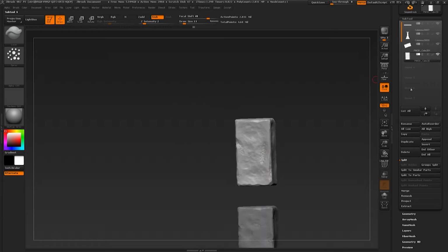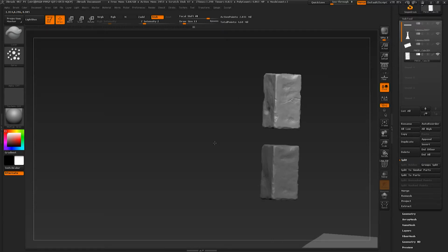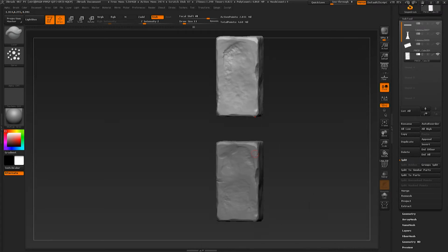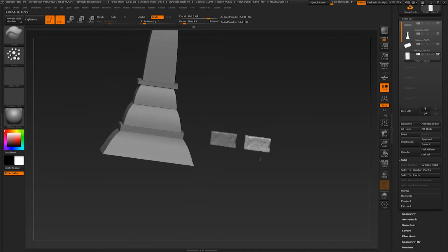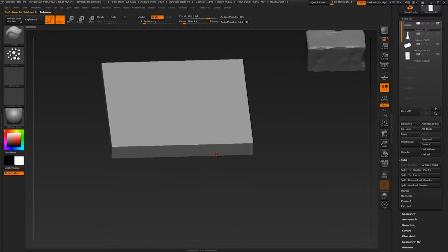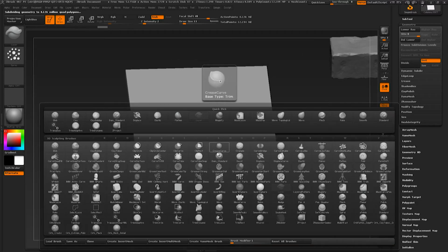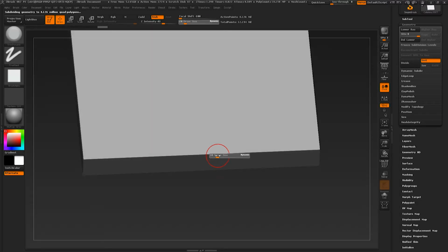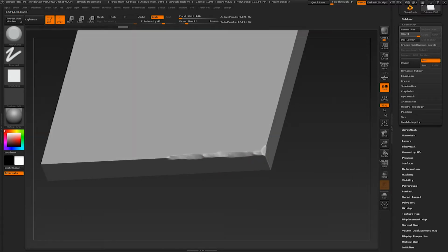Finally, we can start with the slab of stone we're using as a base. I've decided that the material of the entire column should be stone, but you can add screws, metal rivets or whatever you want. The process to add the detail for this part is the same. Subdivide the piece 5 times without SMT activated. Then, to soften the edges a little and so the brushes works better on the corners, add 2 more subdivisions with SMT activated.